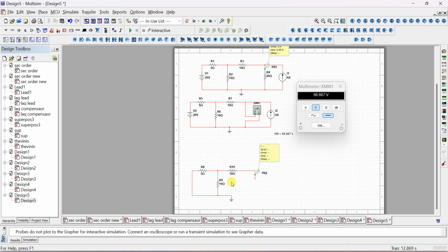So theoretically it is equal to 5 parallel with 10. See here, this is short circuit now. Between these two nodes, 5 ohm is there, 10 ohm is there. So 5 parallel with 10. What is the equivalent resistance of 5 parallel 10? It is 5 into 10 divided by 5 plus 10. So the parallel combination of R1 and R2 is R1 R2 divided by R1 plus R2. And we are going to get some equivalent resistance that will be in series with this 10 ohm.